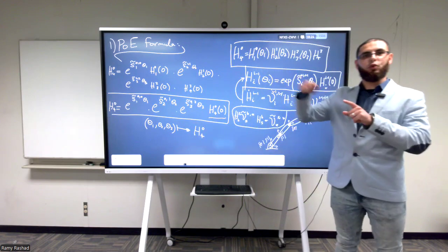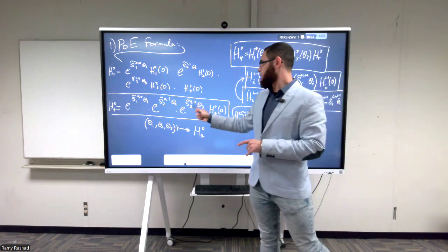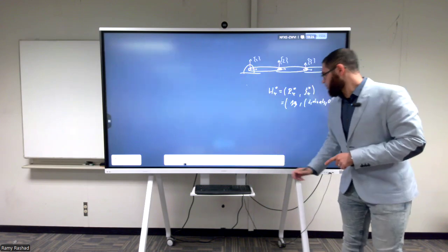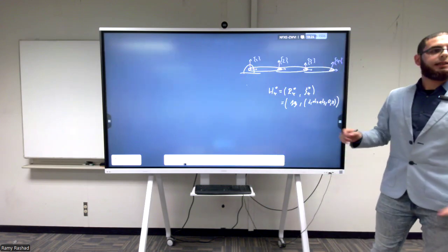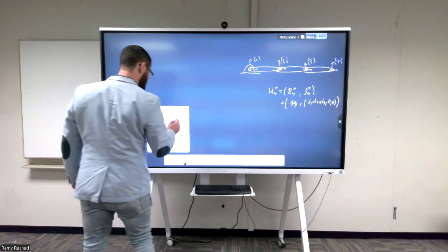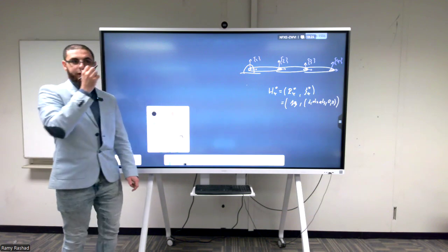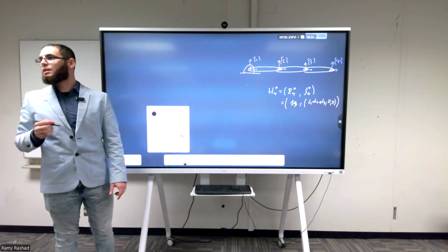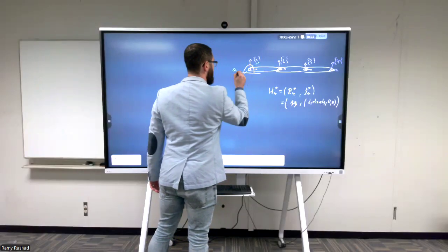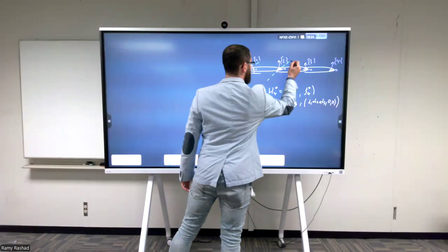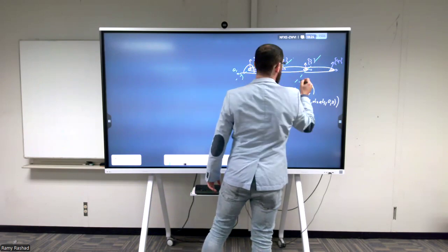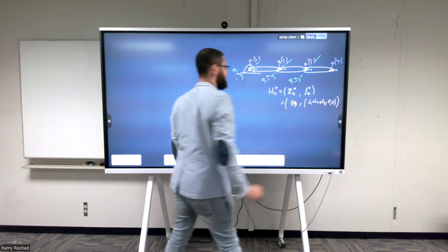What is now this 32? What is this axis 32, axis 21, axis 10? Let's go to this picture. So this robot, the joints that we have, the first joint is what kind of joint? It's a revolute joint, right? Around which axis is it rotating? Around this axis. So this is theta 1. And this joint is rotating around this axis, theta 2. And this joint is rotating around this axis, theta 3.